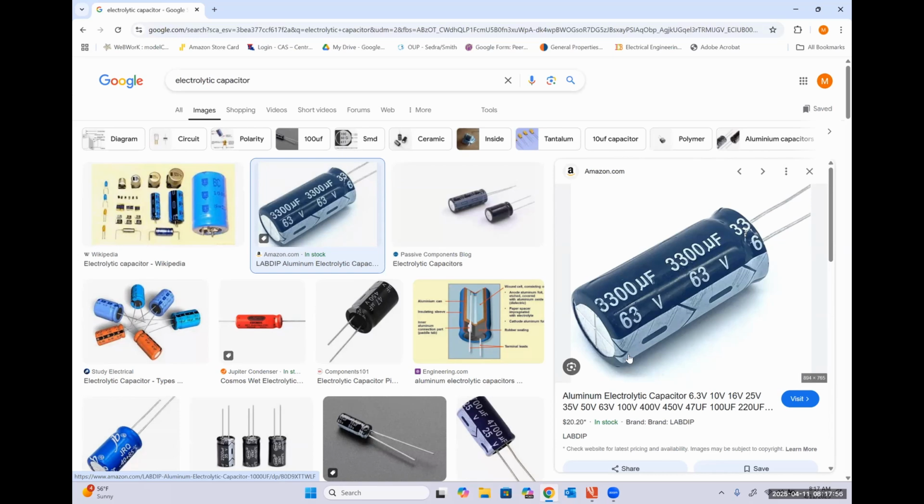Those score lines are to allow that top to mechanically deform to relieve some of the pressure when this guy bursts because it was connected improperly or saw a negative voltage across it when it should have only seen positive voltages. So there's something physical on here that we can literally see to indicate that this capacitor has gone bad. That will essentially dome over because those scores make that diaphragm effectively very easy to deflect.